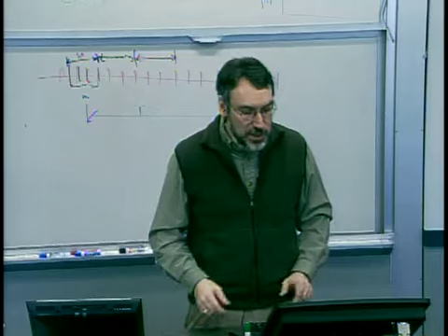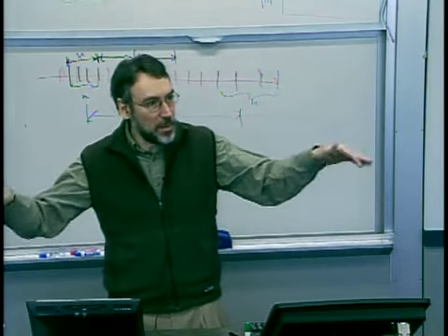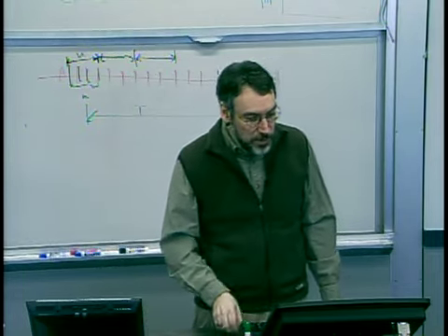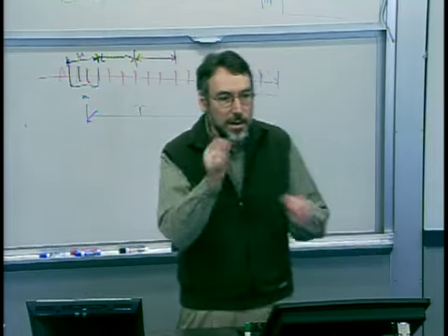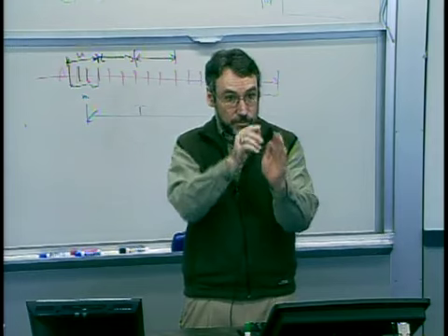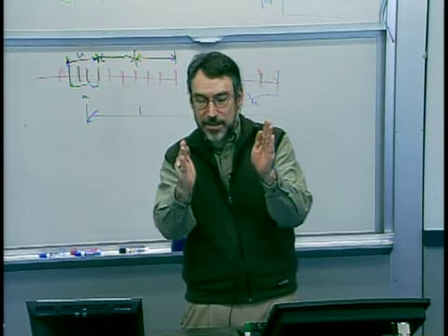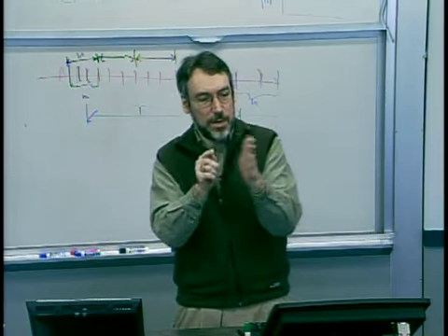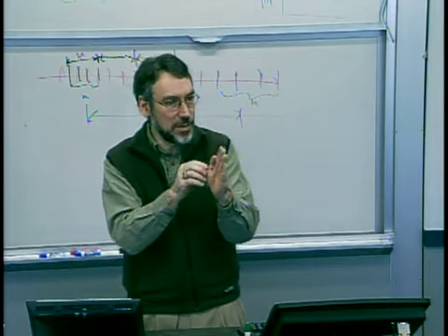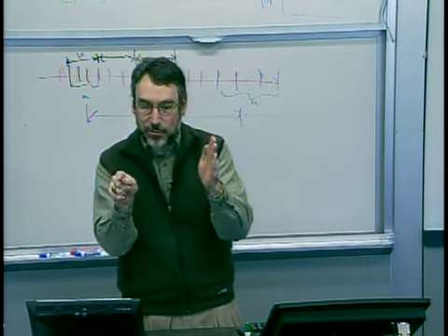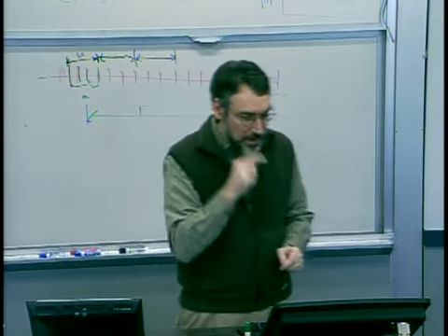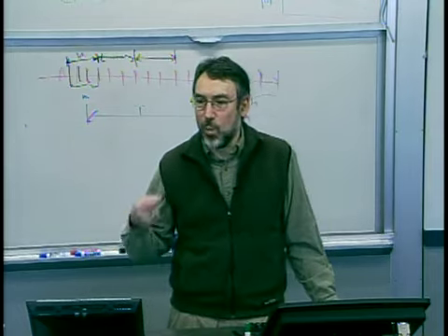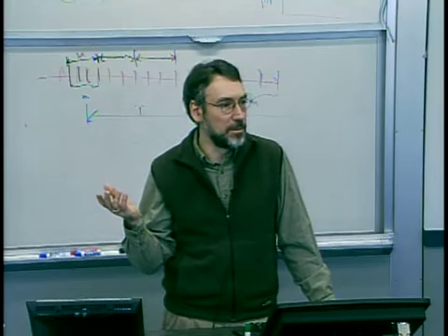Right? But just to give you a feel, then, for these probabilities of non-conforming parts and what kind of CPs or CPKs those correspond to, just recognize that a CPK of 1 corresponds to a 3 sigma tail right at the spec limit, a 3 sigma tail off of whatever my mean is. So I might be off target, but 3 sigma out from the process mean, that's 3 sigma. Think of this as the number of sigmas, right? And that corresponds to about 1 in 1,000 parts falling outside of our tail.